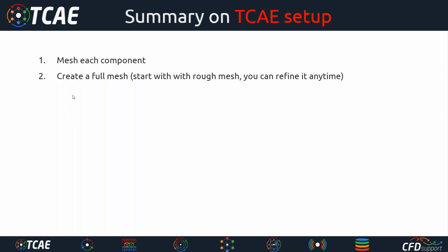That's important. Once you have a full mesh, we definitely recommend starting with rough meshes, because you can refine them very easily anytime. And of course, as you know, fine meshes increase the simulation time extremely, and that's what you do not need in the beginning of the project, because you want to be quick. You have to take quick lessons. You have to really be quick in your simulations and later judgments, because no project is ever done by creating just one mesh, making simulations, and having perfect results. This is how it does not work.